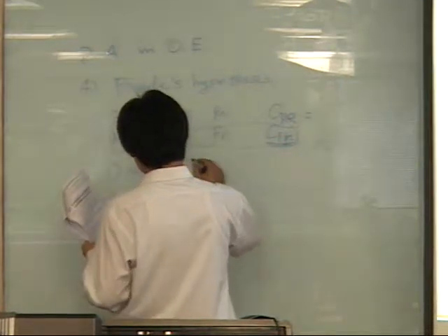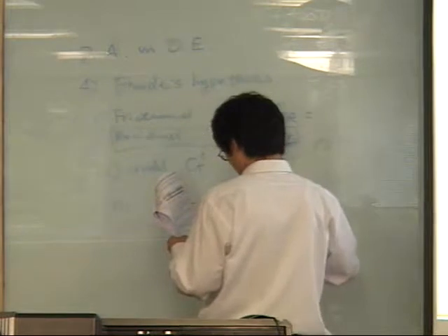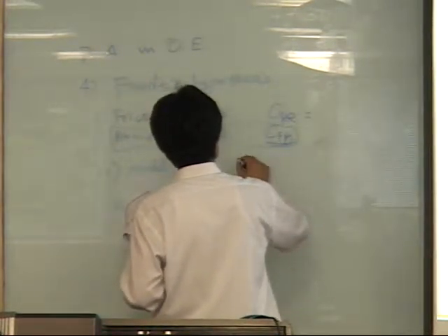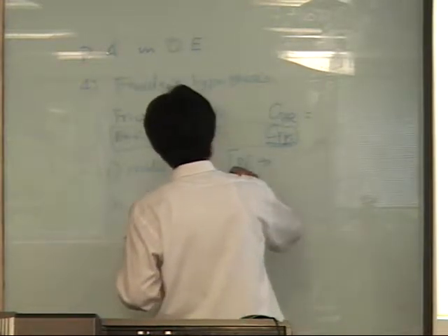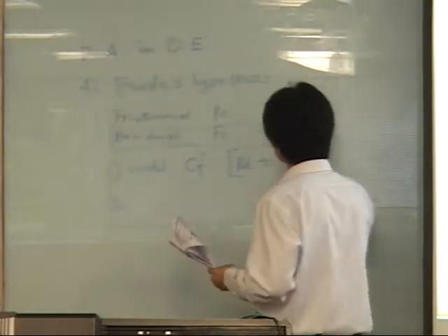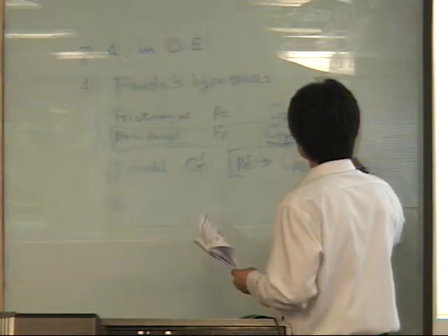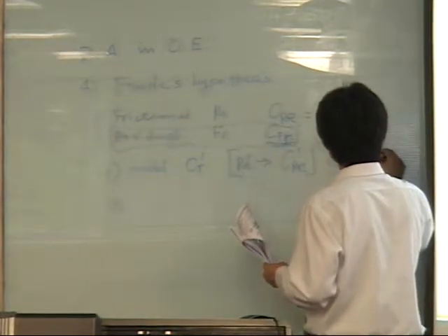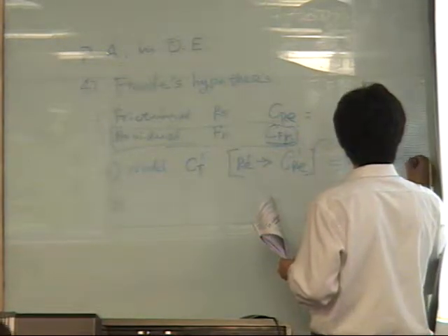in the model test, we measure the total coefficient. We have this Reynolds number, and based on the recommendations of ITTC or whatever, we can figure out this one. Based on this, we can have the residual coefficient computed, right?